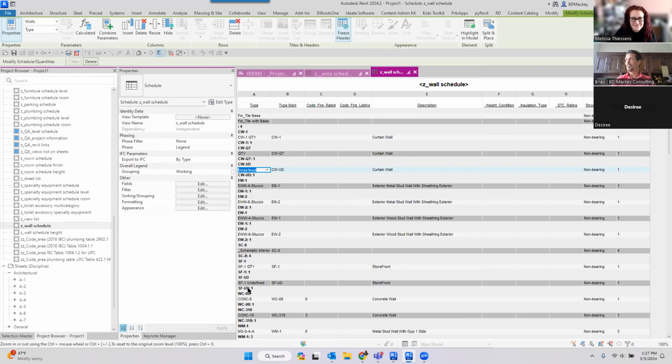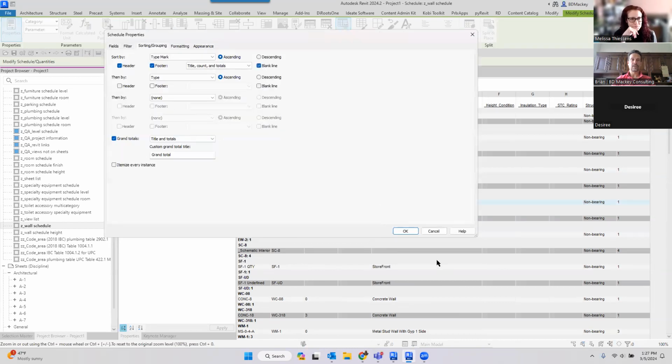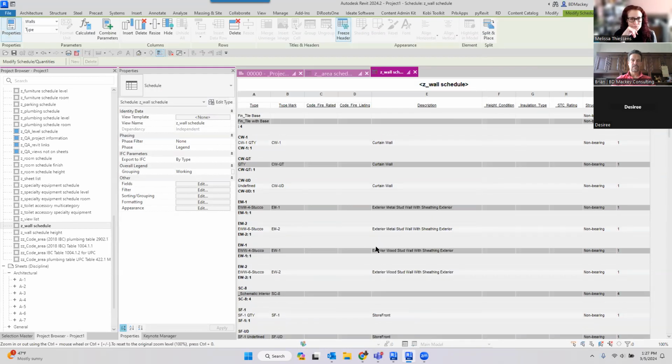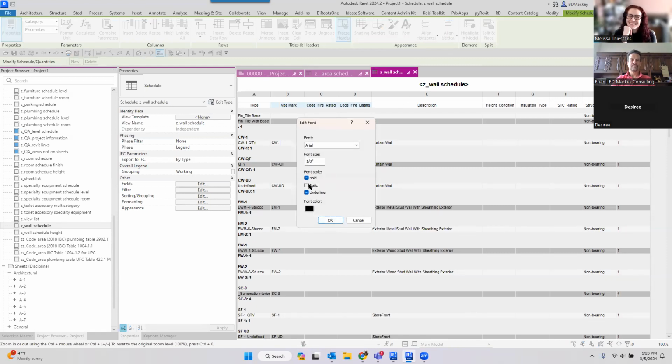That's great because for years this has been a question when people came up: how do you make that bold as opposed to the values? Yeah, I gave him a golf clap also. That's pretty good. I'm gonna put a blank line so it's easier to see. That's very interesting. So then the values are actually grayed out. Nice. So bold everything, select that all up here, unbold it, because it doesn't select the headers, then come back up here and rebold all this. But if you do that in the template, then you should be fine.